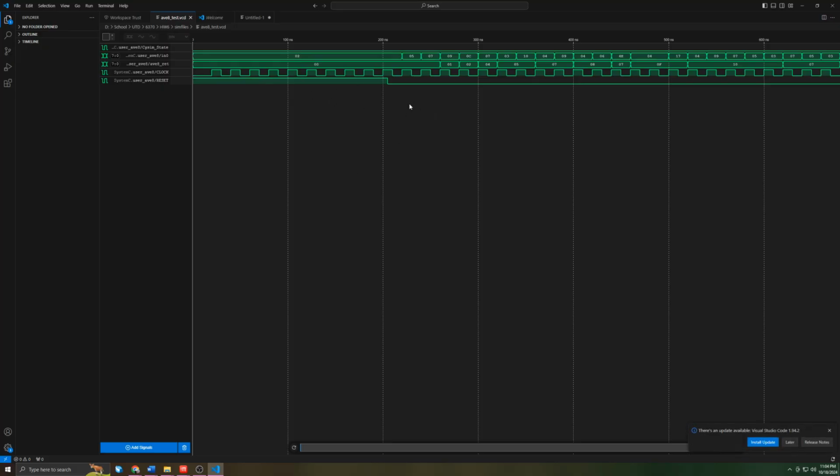So now that I have the VCD file open, you can see right here that it takes an input of 2, 5, 7, and so on, and what it returns is a 1, 2, 4, and so on, all the way up until it gives you 7 right here. This says 10 right here because it's not using the correct radix. We should set this to unsigned. So you can see that it goes 8, 7, 15, 16, 7, and if we had gone for one more cycle, it would show a 5.